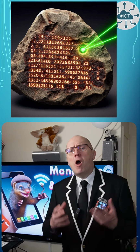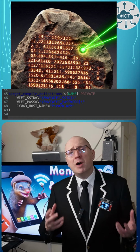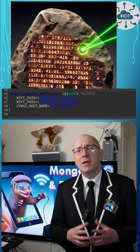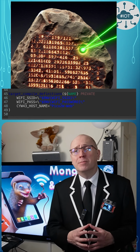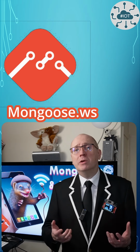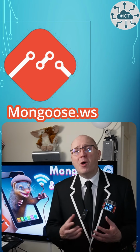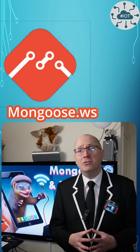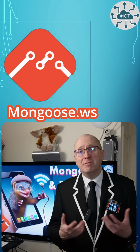Most of the time I hard code my Wi-Fi credentials into my Pico W and Pico 2W projects via a semi-secure approach. That means I can't just give a project to a friend or even demonstrate the project publicly without creating a special build. Using the Mongoose web server, I think I can get beyond that by providing an AP mode configuration web page and then storing the configuration in Flash.